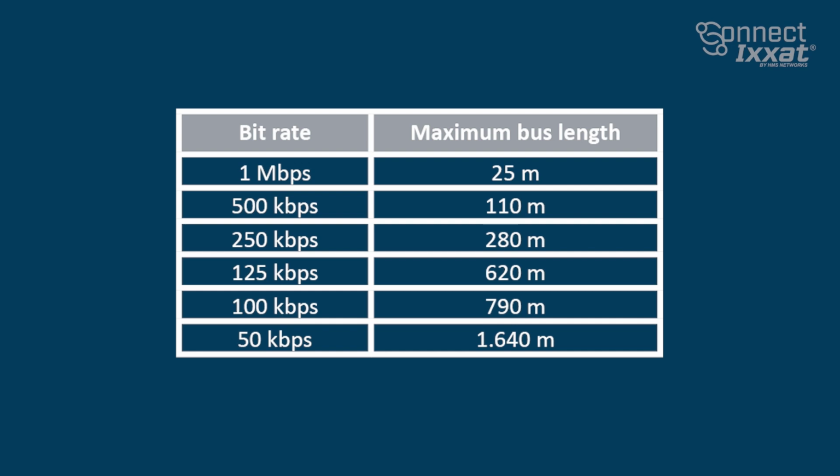This is also caused by its internal logic. If the maximum length is exceeded, the bus must be segmented using CAN bridges or gateways. CAN repeaters cannot be used in this case since they transmit the bus signal directly. This means that the segments connected with the repeaters have to be counted as part of the main bus in terms of signaling purposes. And by the way, using a CAN repeater, you can also create star topologies that change the CAN bus length.